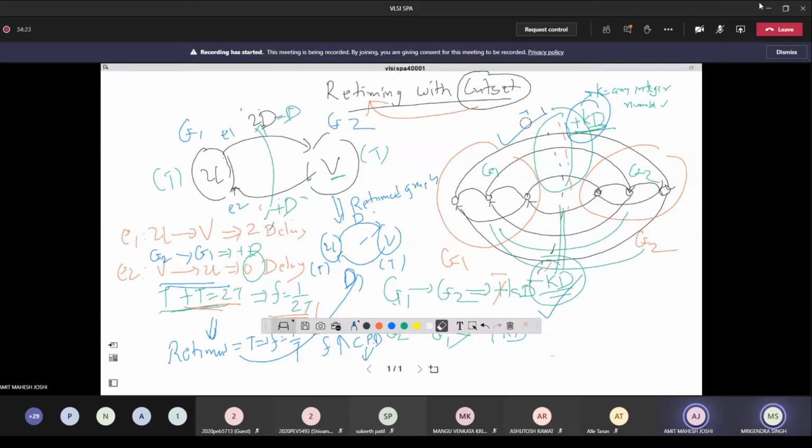That is because in a loop, ultimately the number of delay elements has to be the same. So for the U to V node, as we observed, there are two edges. So either one of the edges has a D, and by applying retiming only, you can shift your critical path, but the performance of the circuit is still the same.